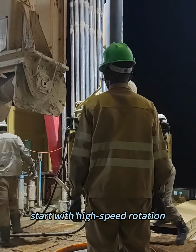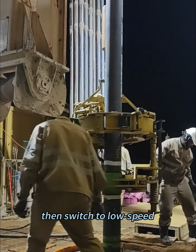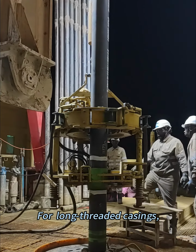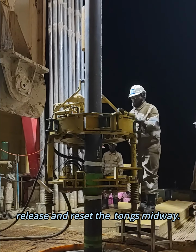Start with high-speed rotation, then switch to low speed once torque exceeds the display value. For long-threaded casings, release and reset the tongs midway.